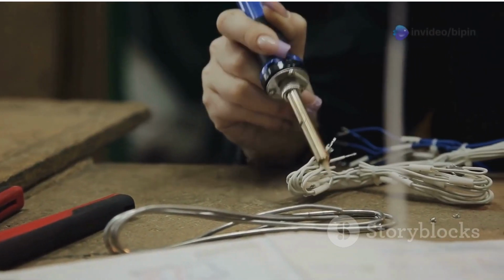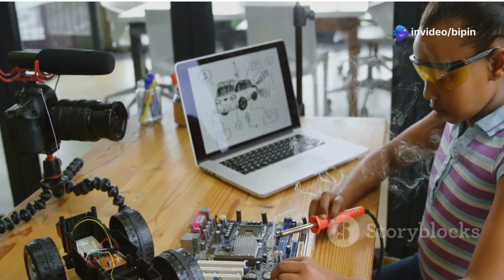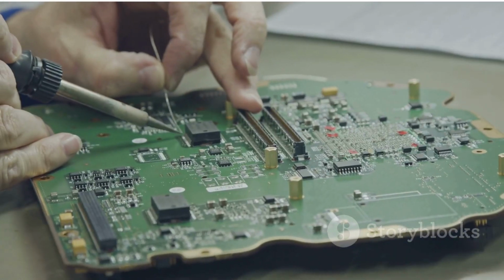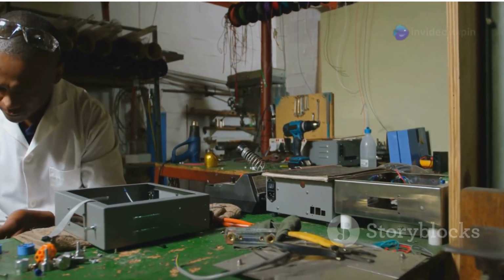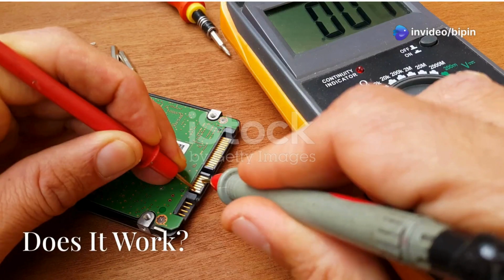You'll need a soldering iron, solder, and a few other tools. There are many online resources and videos available to teach you the basics of soldering. Take your time and be careful when soldering, as excessive heat can damage components. Use a fume extractor or work in a well-ventilated area, as solder fumes can be harmful if inhaled.